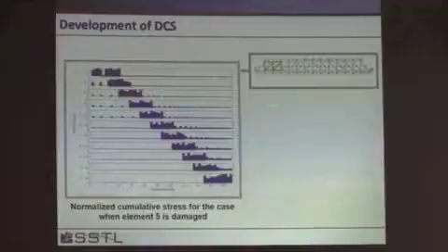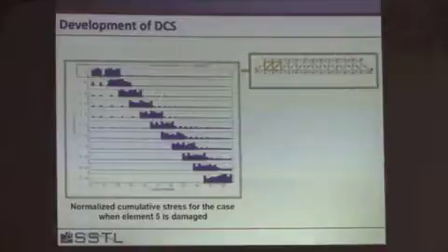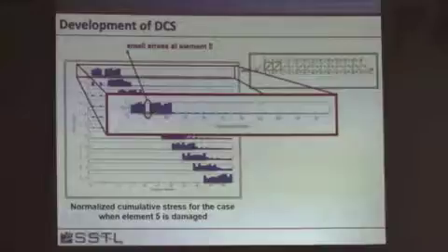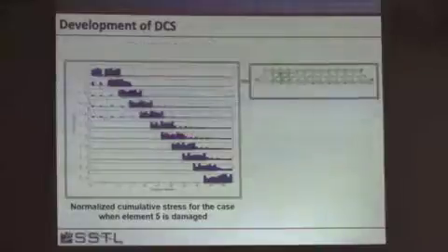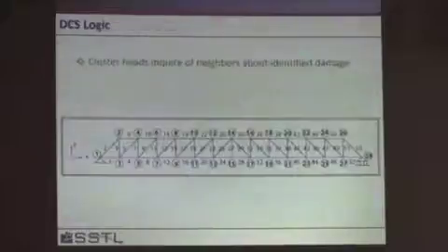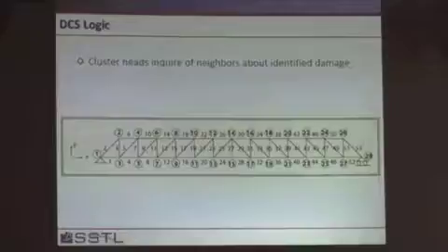And so what you see is associated with this element, and we find damage here in element number 5. You can see element number 5 has small stress. We do this again for the second group, but there's no damage. Element number 5 is right here, it's that diagonal, and so it's not in this sensor group, so we don't have any damage found.